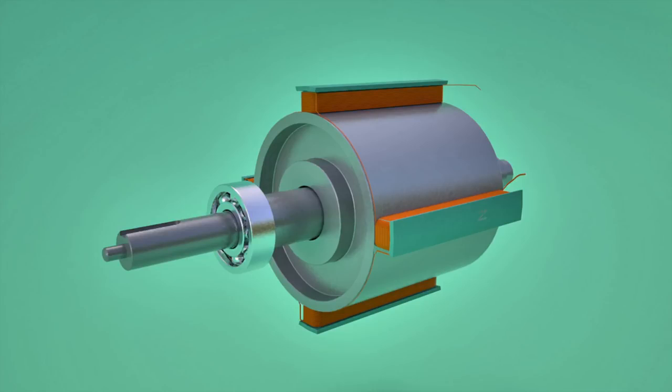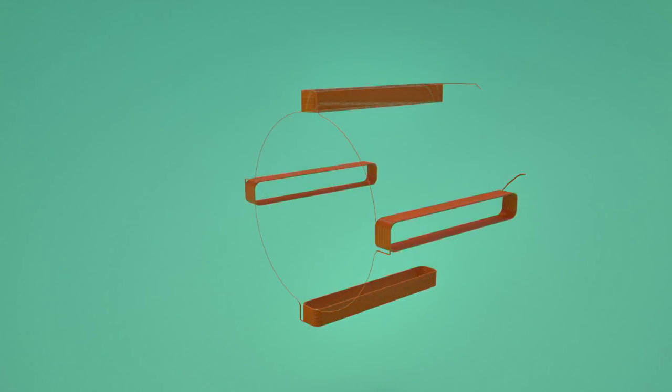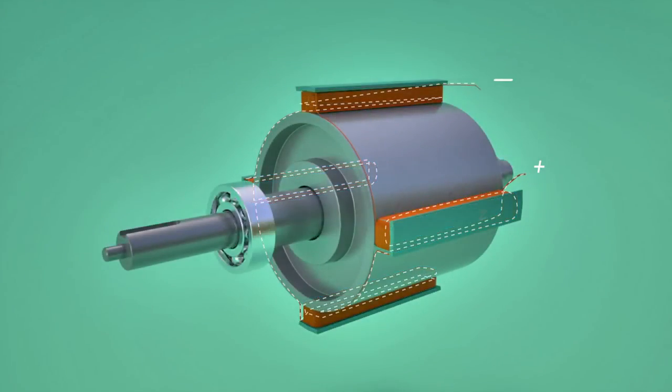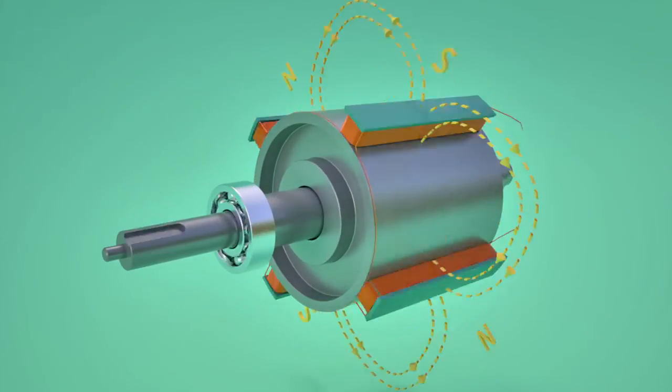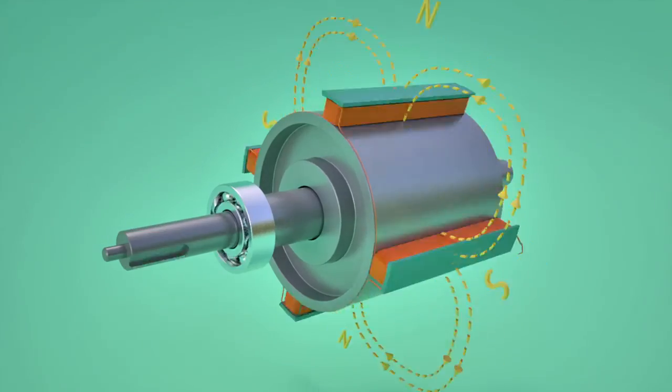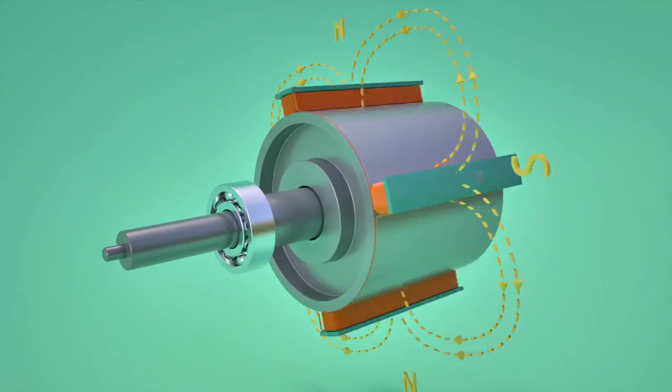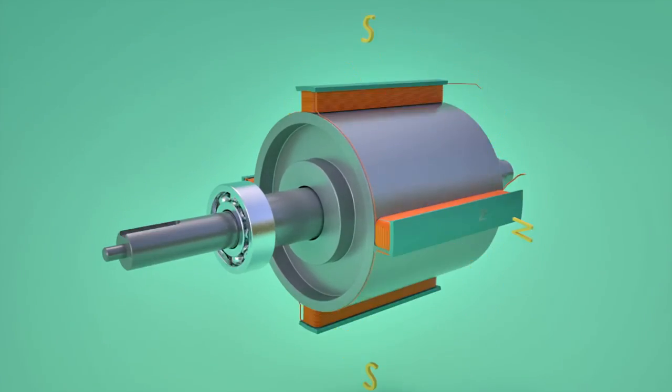Kind of rotor shown here is known as salient pole rotor. For gaining better insight of its working, let's consider a rotor with just 4 poles. Rotor coils are excited with a DC power source. The rotor is made to rotate by a prime mover. This makes the rotor flux also rotate along with it, at the same speed.